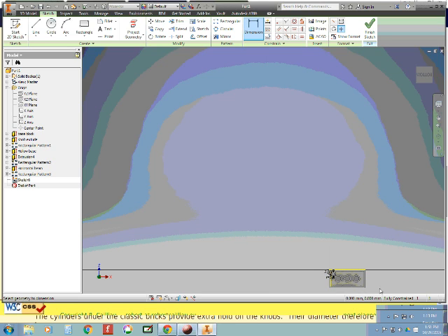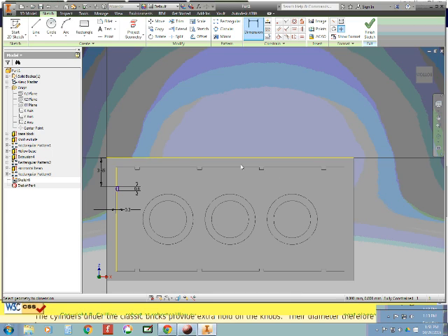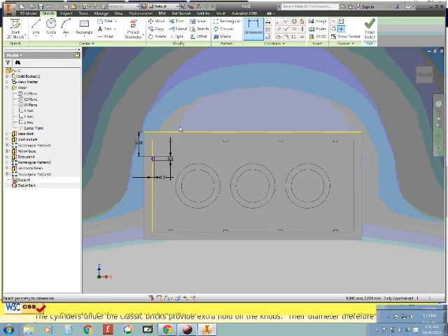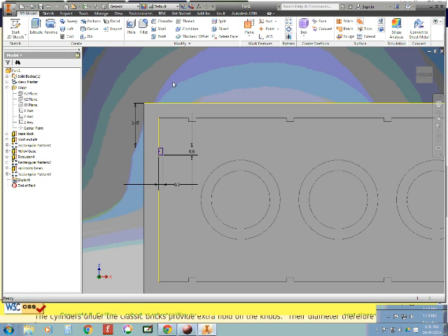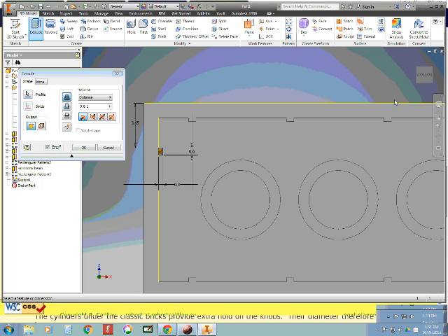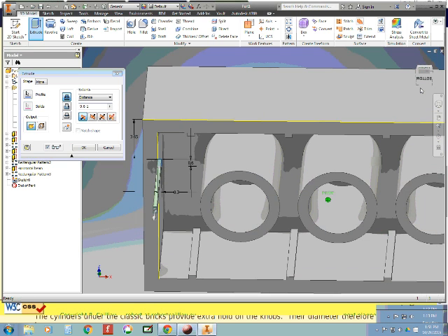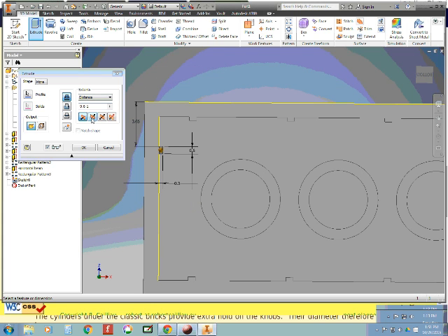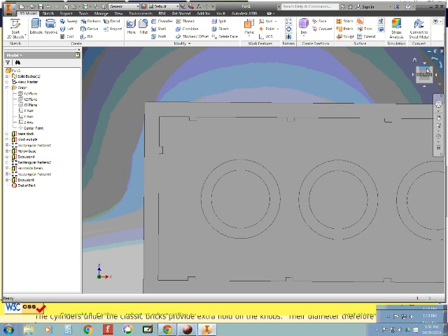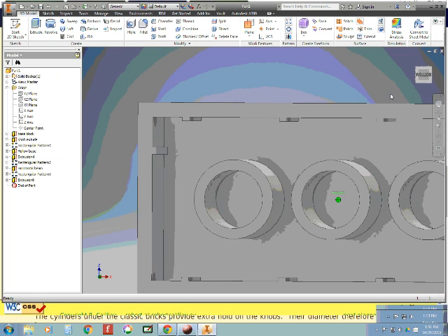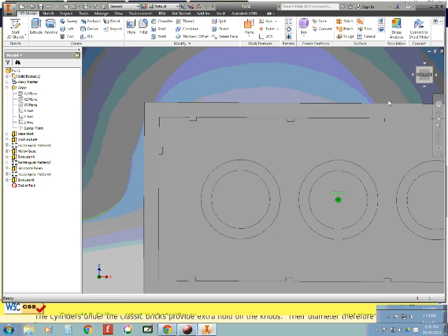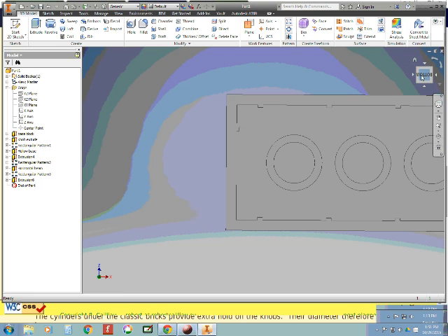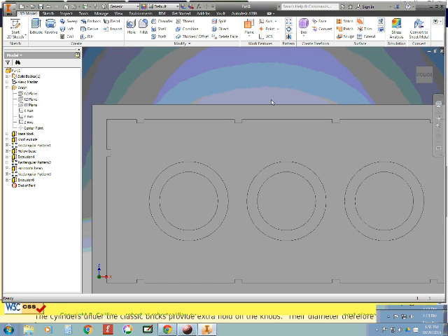So we're now ready to extrude this and then make the pattern, and then this brick is done. So right click, and again I can get out of the dimension tool and finish my 2D sketch in the same step. And right click and choose extrude. It has my geometry selected, but again it's the wrong direction, so we want to go back and click OK. And there is one of my vertical beams. And now we just need to make another rectangular pattern.